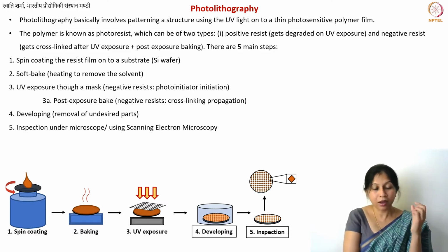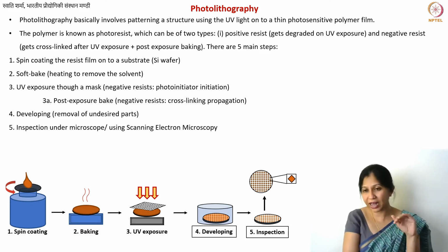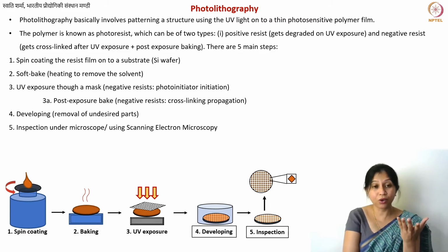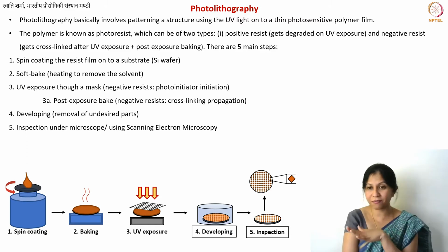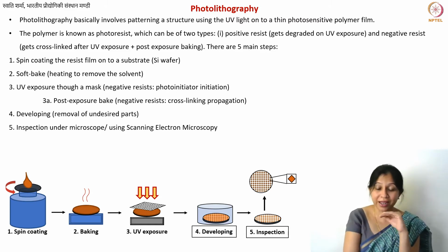But here is the thing, the material that we obtain at 900 degrees has properties very similar to glass-like carbon. For example, number one, it's prepared by coking, so it has a flat surface. That is something which is very important for us. In fact, in this case, the surface is very, very uniform and flat because you prepared it by spin coating. So you see this photolithography technique, you already prepared an extremely flat film. And all your structures are film-based structures. They have a flat surface.